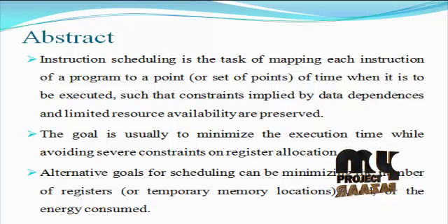However, less attention is paid to temperature management in these schemes. Although low power design can reduce the chip temperature by reducing the average power density, localized peak temperature does not necessarily decrease. Some low power mechanisms conflict with temperature management, because temperature is influenced not only by power but also by the area and power distribution of compiler assisted leakage power management.